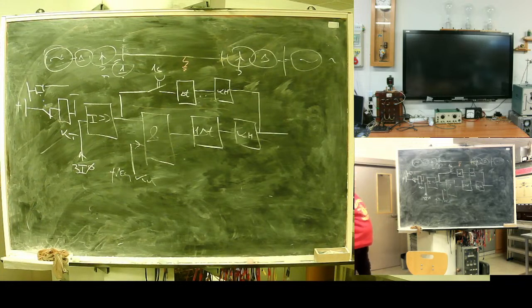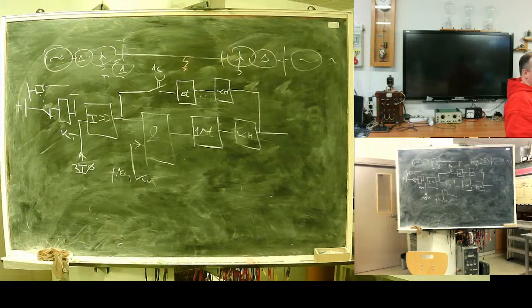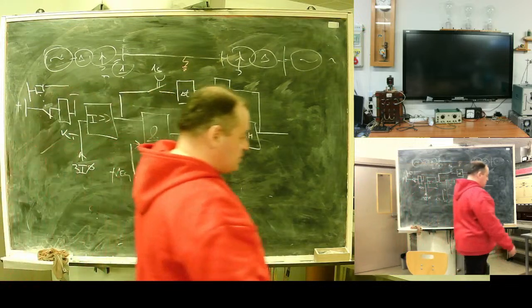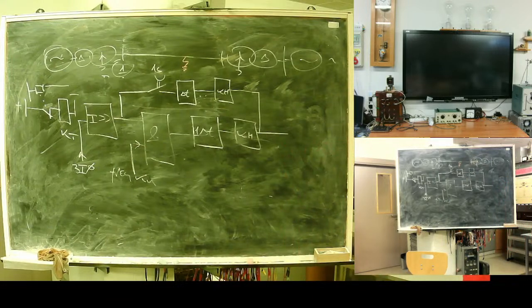Idea, it's a fast circuit activated for approximately usually 1 second. It's activated when circuit breaker is off and remains active for 1 second after switch on. This is speed up for switch on fault condition to make this protection operate instantly. It was done because this was a basic protection, main protection, better name it main protection.